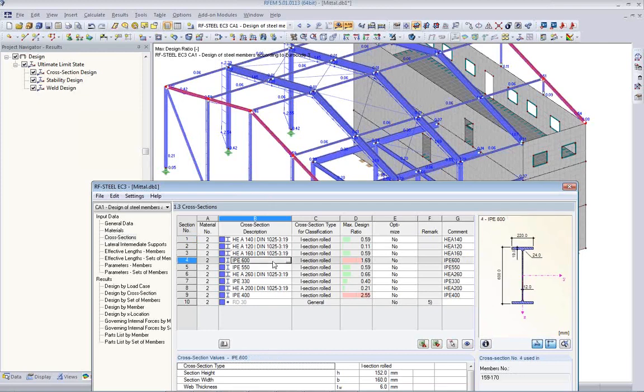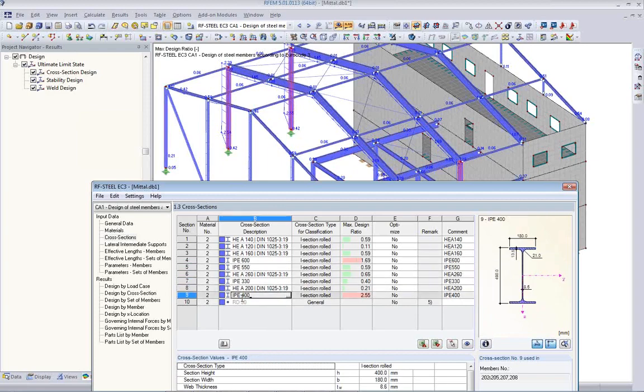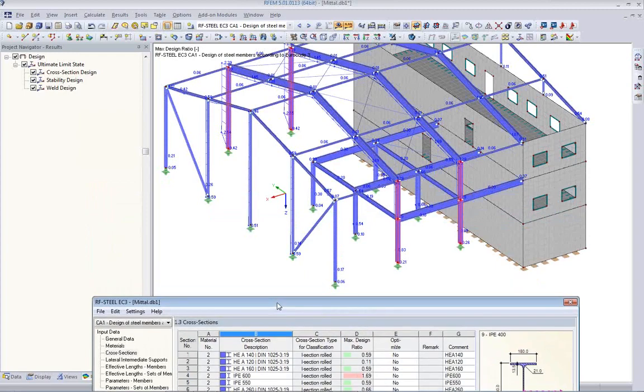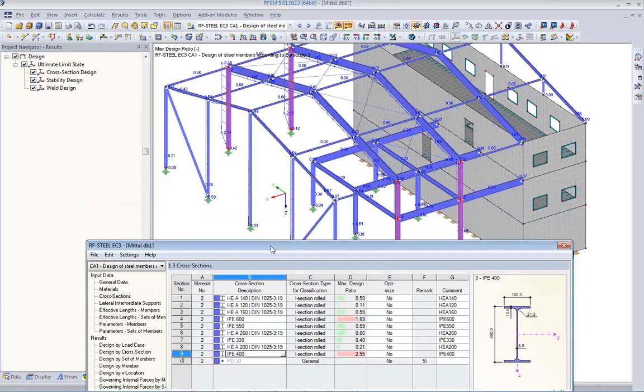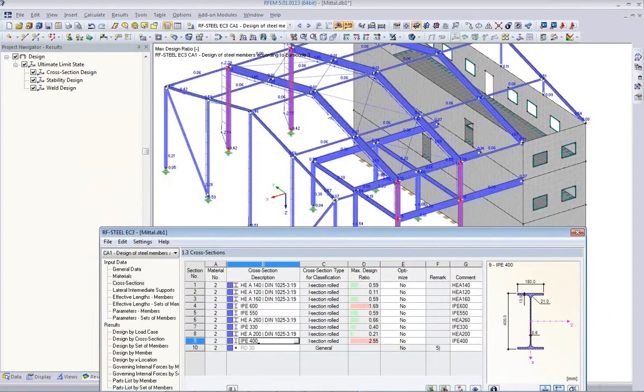These seem to be okay, but these main girders are a problem. Then we have the cross beams here, which are pretty okay. And I'm missing, actually, now here they are. These are the main columns here, which are not so good. We have IPE 400 here, and it's no good. So something needs to be done.